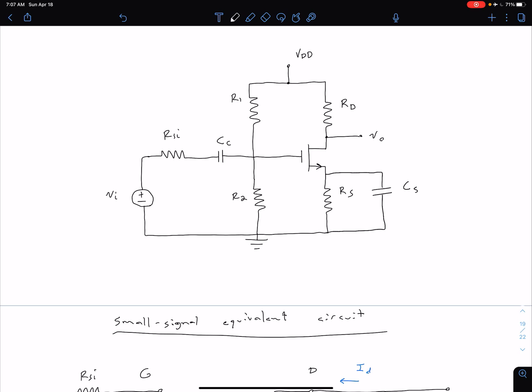And what we're going to see in a later course is that it's actually even better to just bias these amplifier networks using a current source. And so you can look a little bit more on page 225, so that's discussed, but again, this is something we'll talk about in detail in a later class. So current source biasing is typically what's going to be done, particularly if these amplifiers are going to be used on any type of IC. So current source biasing.